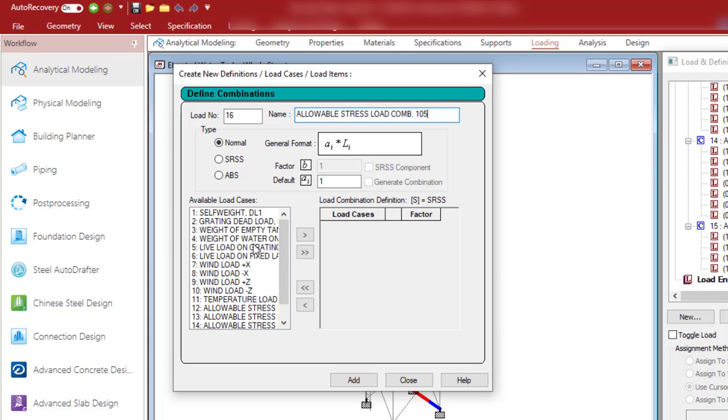The reason why the live load is not added here is we want to know what will be the wind effect on the structure when it's not carrying anything. A structure that is being constructed, maybe they just finished construction and there is wind. So what will happen to the structure? Because when you load the structure, it helps to stabilize it. It has to work against wind. So the structure is more stable when it has a load on it.